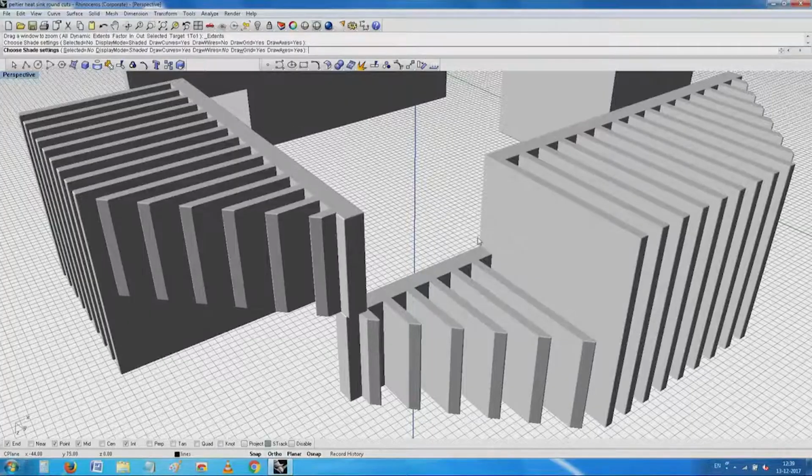I have a little access to the corners here, and once I have access to the corners here, either I can leave a gap between these two heatsinks, top and bottom, so that I do not need to drill the heatsink in any way. Alternatively, I can make a small half circle, a semicircular groove here, by which it can go inside and directly it can take in one of the corners.